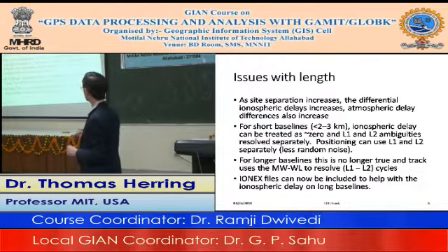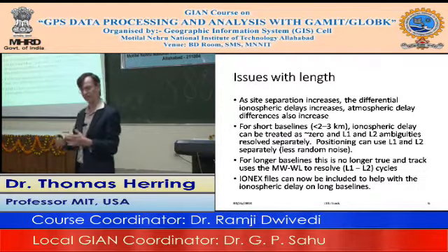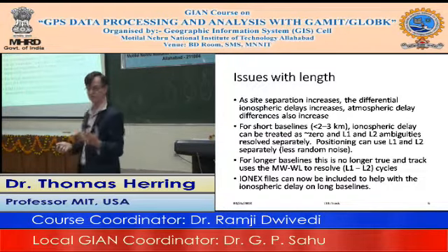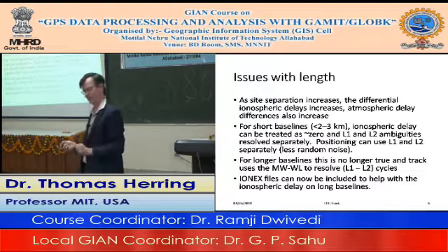So as I said, baseline lengths shorter than 2 to 3 kilometers can basically be treated exactly as 0. The L1 and L2 get resolved separately, and the positioning can just use the L1 and L2, and that has less noise in it. So as you go to longer baselines, you need to use this Melbourne-Wübbena wide lane, as we spoke about, to resolve that difference. And again, these IONEX files, which we haven't looked at, are estimates of global maps of the ionospheric delay, and those can be included to help resolve it on long baselines. So if you're doing anything more than 300 or 400 kilometers separation, we certainly recommend that you download these files. And again, the help tells you how to do that.